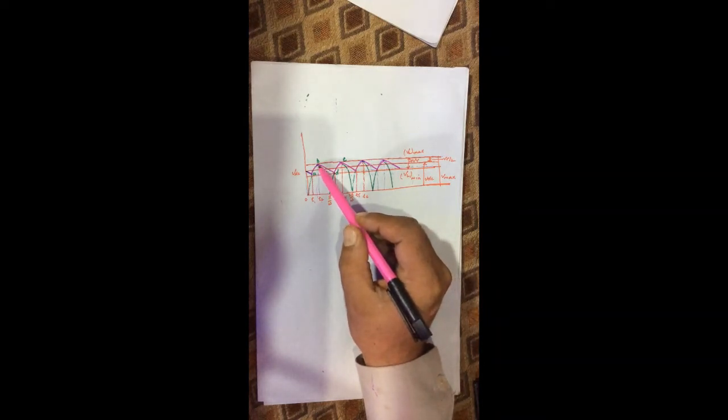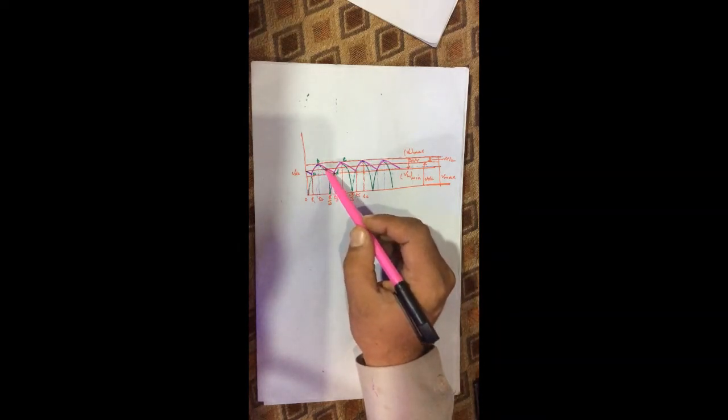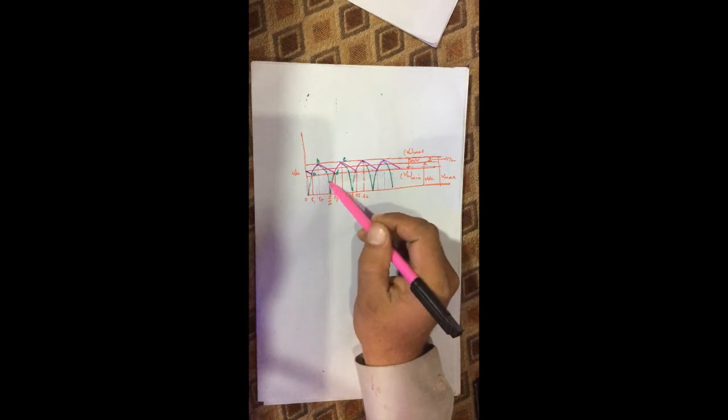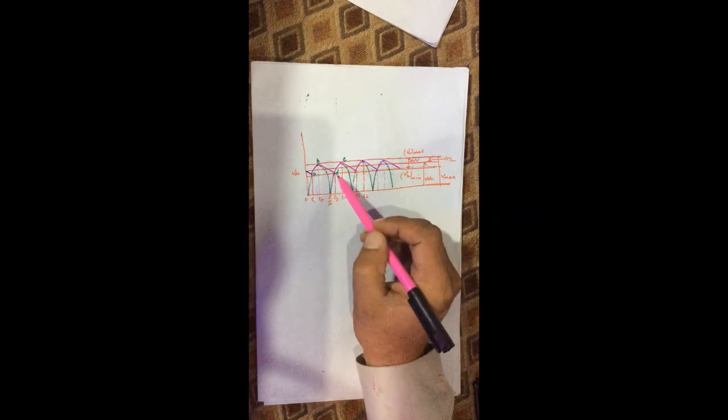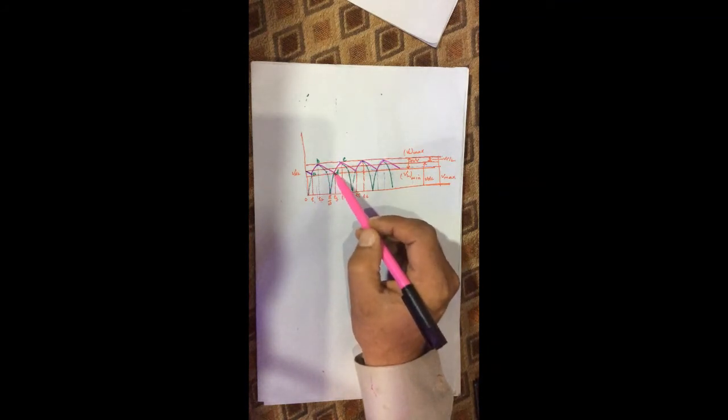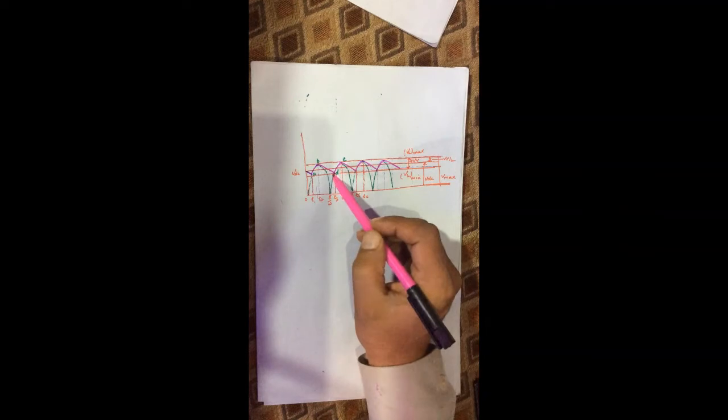The capacitor gets discharged through the load resistance RL and maintains current there. From t2 to t3, like from this time to this time, that is from B to D, the capacitor discharges slowly, because the discharge time constant is large, to flatten the curve.